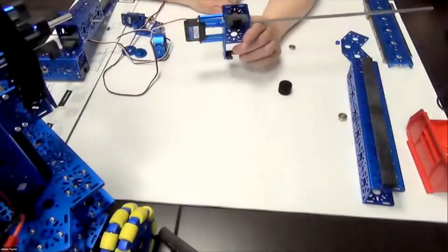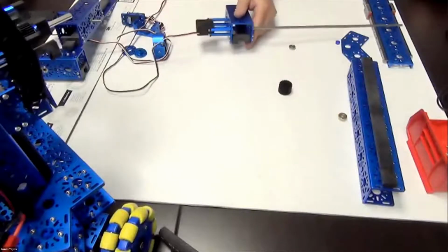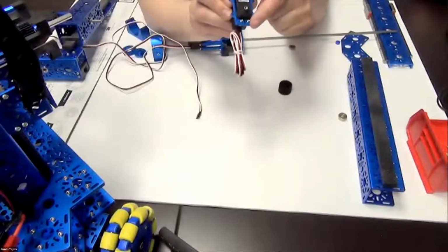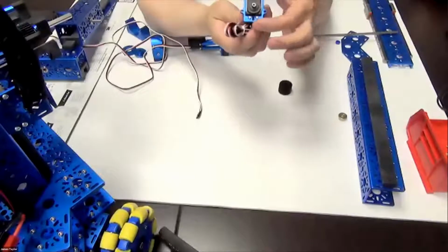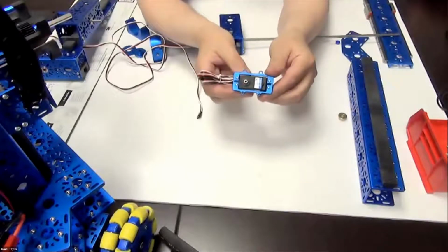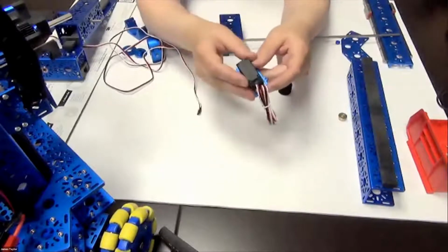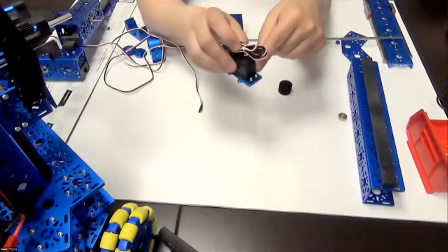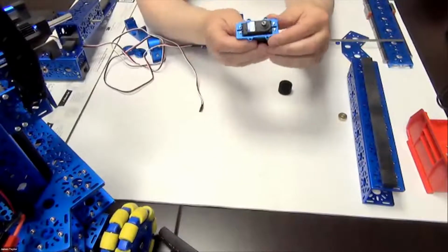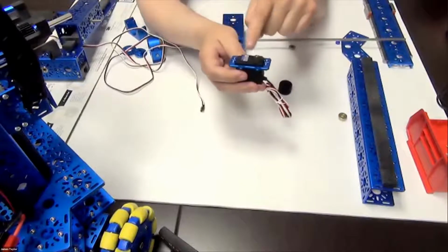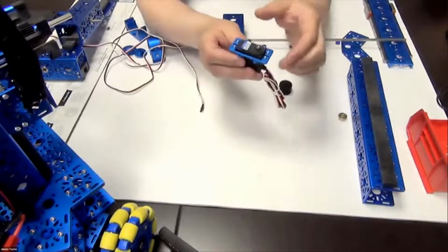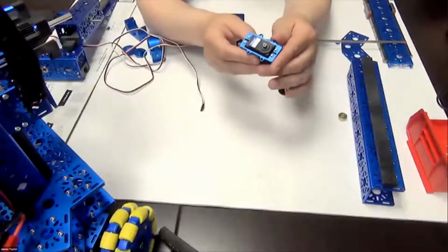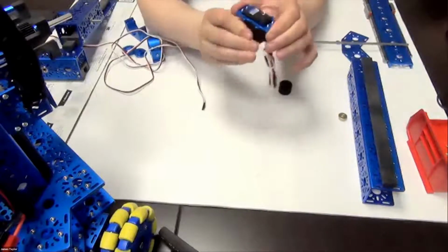So if we take a look at it, basically what happens is this is the motor, here, and this is that standard front mount bracket. The motor fits up through the front mount bracket, and then there are 4 socket-headed cap screws here that we can use to secure the motor to the bracket. These are your through holes right here on this side. So what this does is it provides a firm mounting point for that motor, and it also provides stability for the motor.